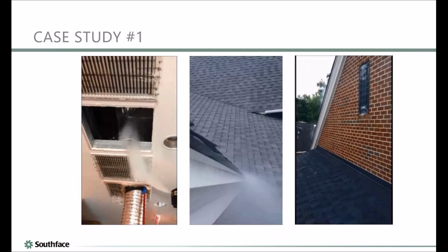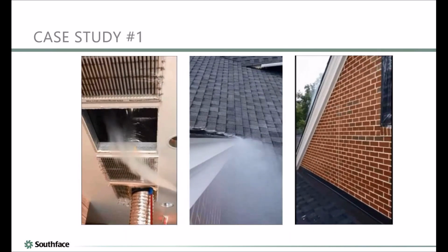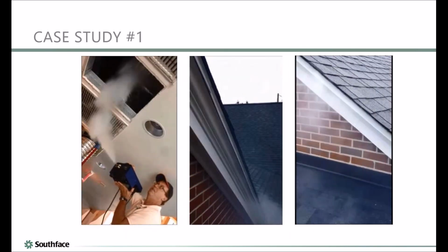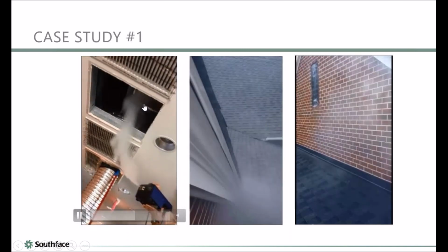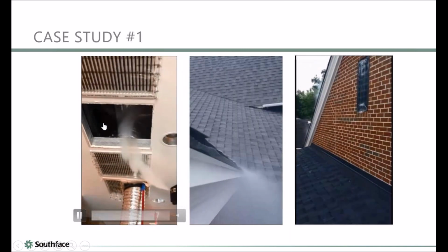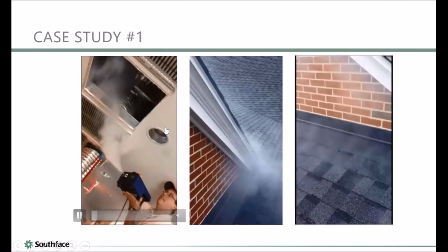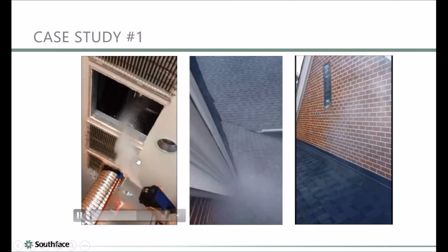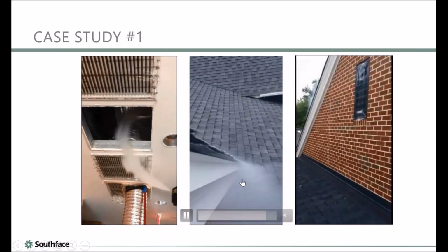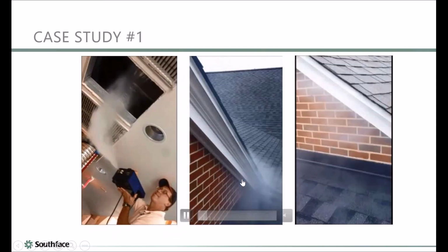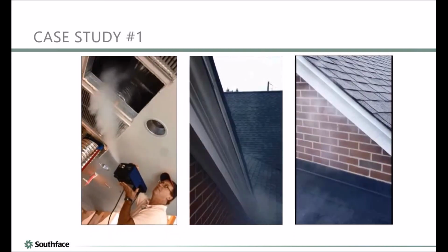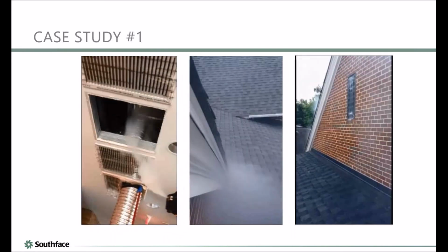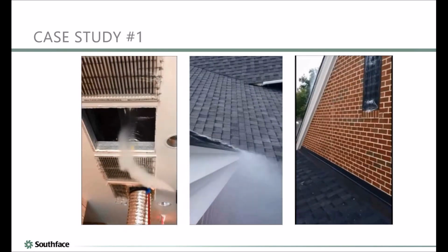And initially, the thing we're blower door testing. In this case, we're pressurizing the building, and that is supposed to be the return plenum space above there. And obviously, if it was airtight, when we blew air into the building, that fog would not be racing up in there the way it is. But you can see it clearly was not airtight. Right. And there's a lot more going on in that building, but that was one particular issue that it had.